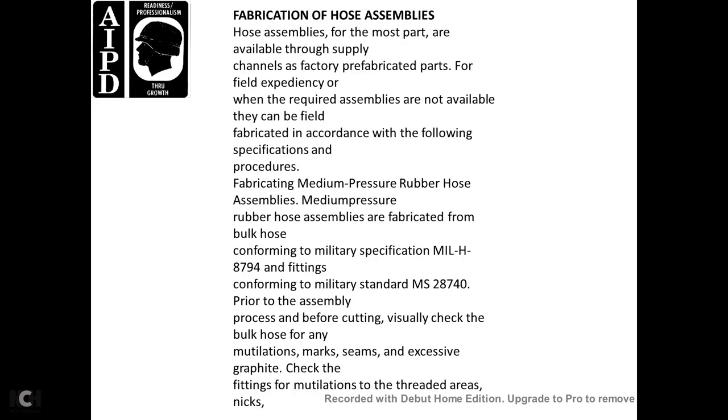Teflon hoses. Installed Teflon hose assemblies must be inspected for evidence of deterioration due to wire fatigue and chafing at the periods prescribed by the applicable aircraft maintenance manual. Replacement of these lines must be made when the following conditions are found: leaking, static leaks exceeding one drop per hour, excessive wire damage of two or more broken wires in a single plait, more than six broken wires per linear foot, or any broken wire in any position where a kink is suspected, distortion, any evidence of abrasion, kinking, bulging, or sharp bending.